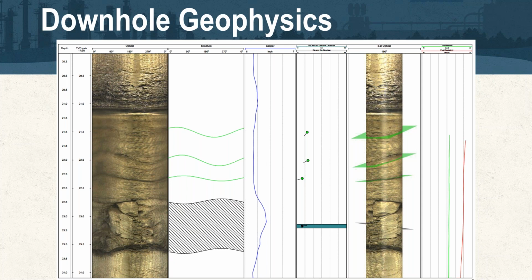And what we've seen at times is that the core location can deflect, or the reaming bit can deflect, and essentially you have a cut in the sidewall of the borehole that prevents getting a suitable seal. So for good best practice, we always recommend completing the core hole at an adjacent location, offset from your open boreholes, just for ensuring that you have the best possible chance of having a nominal caliper size for that specific borehole that you're going to be going back into later.